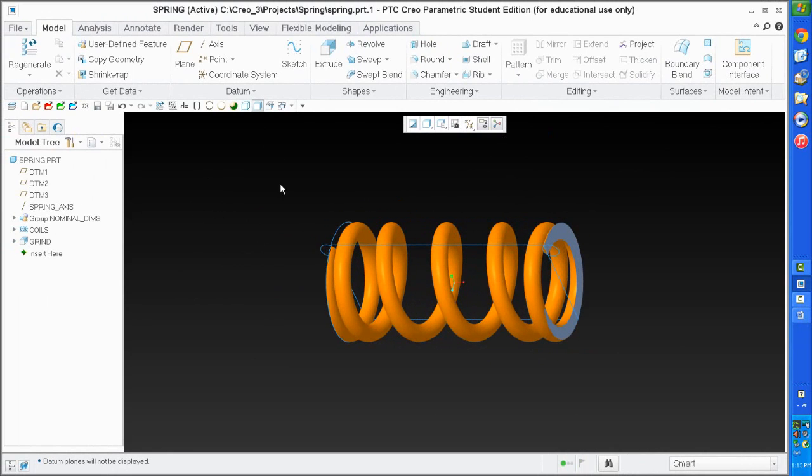That's our spring. What we'll do now is we'll add flexibility, and we're going to also add a readout to tell the user how much force is being exerted by the spring in the assembly, because it's going to be different. It depends on how much it's compressed. So we'll need to add a parameter called rate, and we're going to have to do some things.